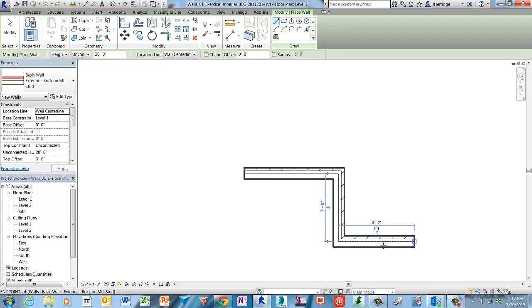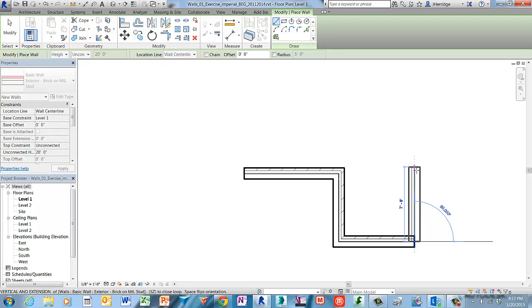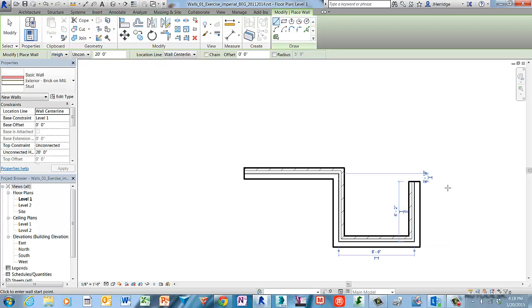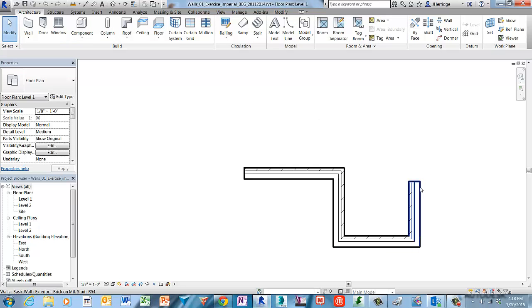And let's go ahead and set that to 8 feet. Continuing on, drag the cursor north on the screen or straight up. You'll notice that when we get back to the location of the first wall we placed, you can see that there's an alignment snap there. That's good to know that you can actually work with precision and create that as a design intent.